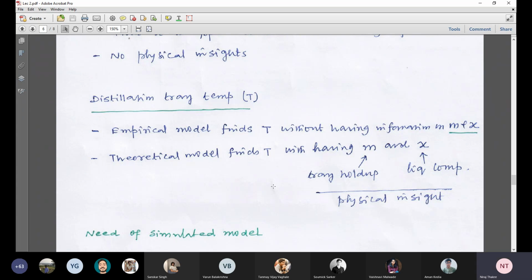So we don't need any information other than the measured control variable. So why are you saying we need a model? If you recall the control configuration, we measure the control variable, and that information is enough for the controller to calculate the control action. It does not need any model.